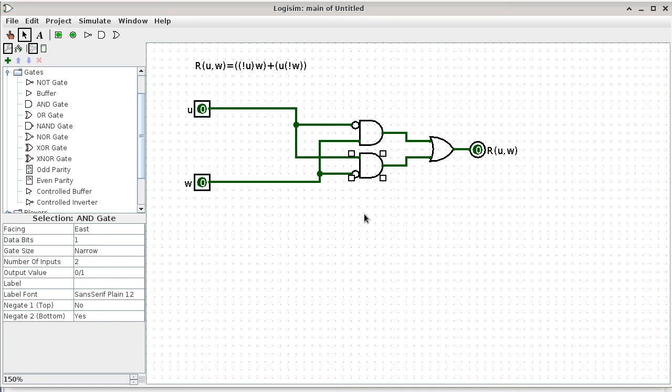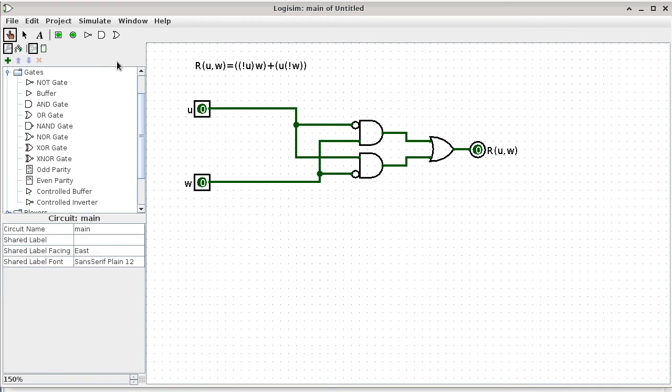So once you build a circuit, the next thing you want to do is to test it. Is it really exclusive OR? Well, fortunately, with Boolean values, we can actually exhaustively test every single case. So we have 0 exclusive OR 0, which is supposed to be a 0. So we are good. To test a circuit, you have to change to what is called the poking tool, or the little finger tool.